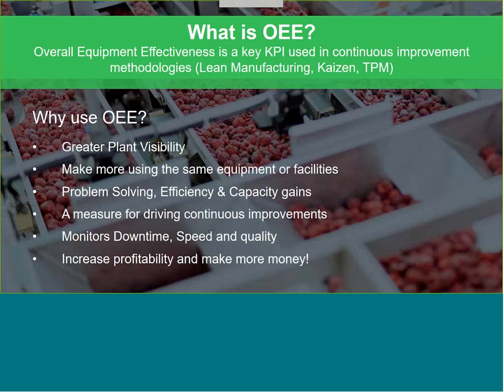It allows us to establish a KPI for reporting, for data analysis, for benchmarking against your competitors, against industry standards. By measuring and improving your OEE, that'll help you to deliver capacity and efficiency gains. It allows you to track your equipment downtime reasons, your speed and performance losses, your quality losses due to waste or rejects, and all of that feeds into helping you reduce your overall cost of manufacturing.